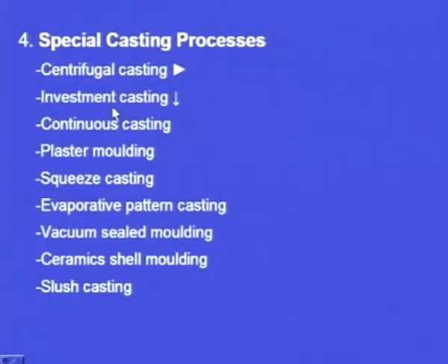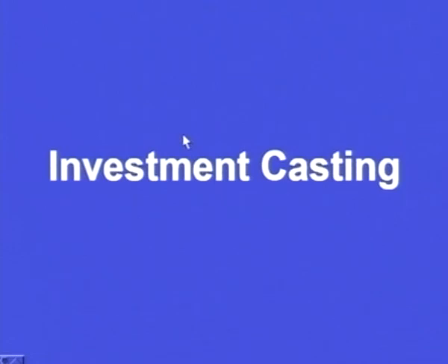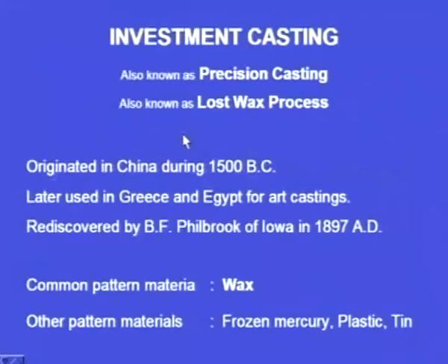So, we are studying the special casting processes. We have seen the centrifugal casting process. Now, let us see investment casting. This investment casting process is one of the important casting processes. Where extreme precision is important, we use the investment casting process. That is why we also call it precision casting,